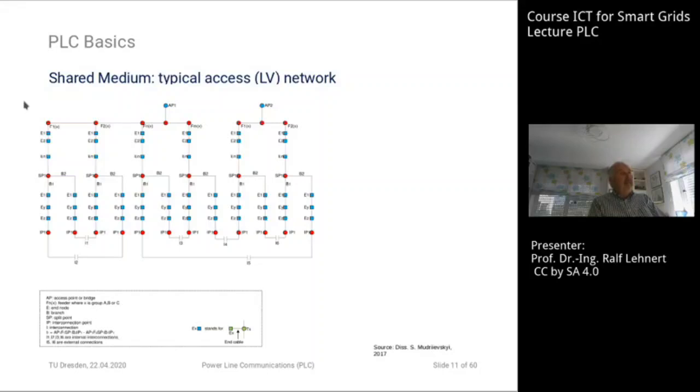So this is an example, a power network, where here we have 2 transformers, here and here, access points where the transformers are located, and then we have feeding points, and the customers, the houses, are these. I should also explain that typically a power distribution network is designed such that in the case of a power outage, let's say a cable is broken, for instance, let's assume that this cable here is broken, then we cannot feed the typical way, but there is a connector or a switch at the end point, and if you close the switch, then you can feed the house here over this way from here.